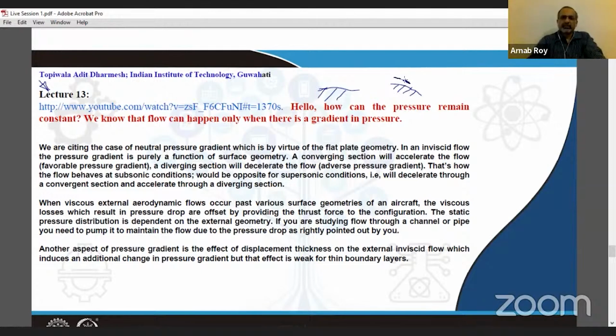So the flow was essentially moving past a curved surface and facing adverse pressure gradient. We also looked at the airfoil lower surface where the flow was actually accelerating. So the dp/dx in the two cases were different, because in the adverse pressure gradient case, this was becoming larger than zero. In this case, it was becoming lower than zero. In this case, it was equal to zero.